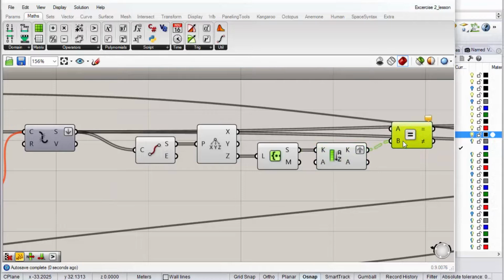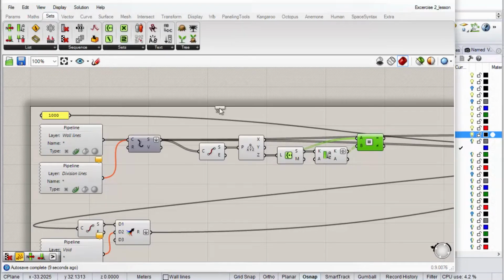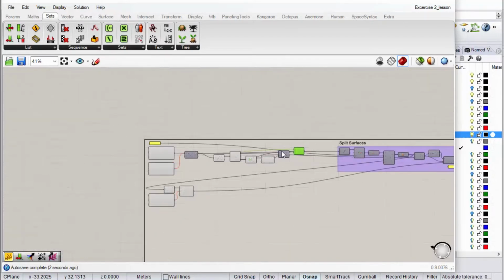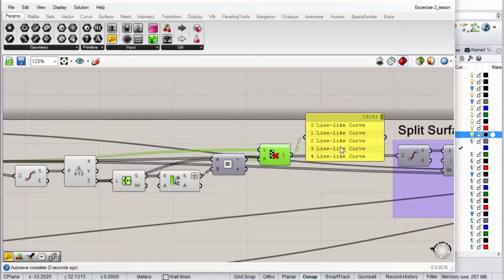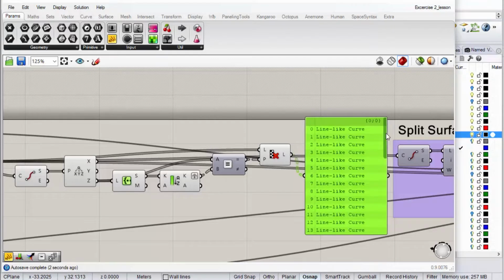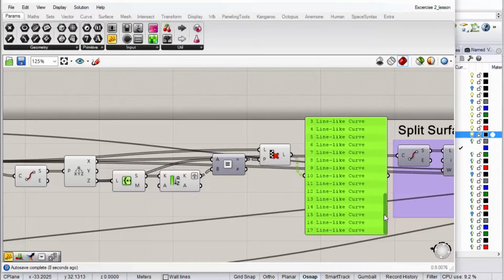try to find for each branch all of the z values that are equal to this height. And if we then take that and use that to eliminate from each branch all of the values that are not at the height specified for that branch, and there it is. We've divided everything into two branches, and each branch has all the curves that belong only to that height.